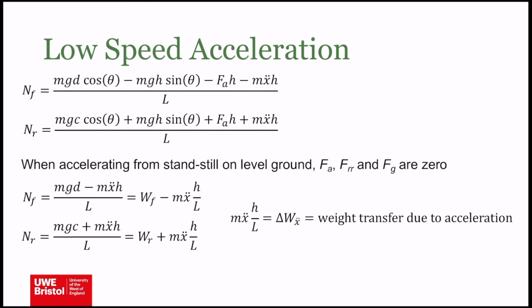So the higher the centre of gravity from the ground, the more weight transfer there'll be. And obviously the longer the wheelbase, the less weight transfer there will be. So a long wheelbase car with a low centre of gravity is going to have a lower weight transfer than a high car with a short wheelbase. Weight transfer due to acceleration.